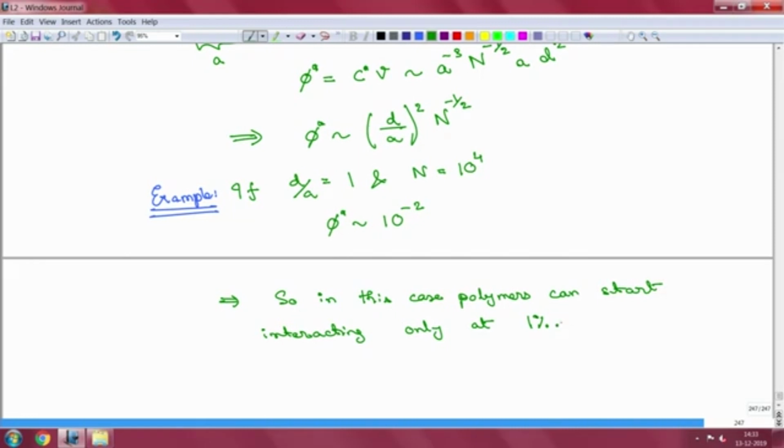This is quite interesting, because typically we tend to think that phi of 1% is a small number, but for polymers 1% can be very, very large. They can be extremely significant, which is why for the kind of polymers that we were using, at 1% you can actually end up getting very significant viscoelasticity. So, we should not bear the notion that for polymers, dilute means 1%. 1% need not be dilute.